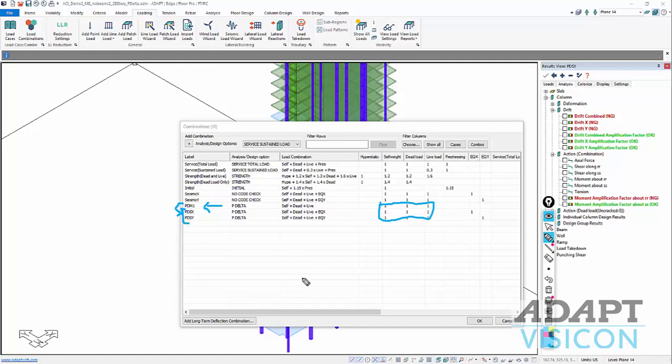If you want the program to uniquely solve each Pdelta combination separately, we would remove the master combination from the list, and we would only solve for Pdelta SX and SY. Each would allow the program to solve its own unique geometric matrix and then produce a solution for these 2 combinations. So these 2 combinations are sourcing this combination for the production of that matrix.